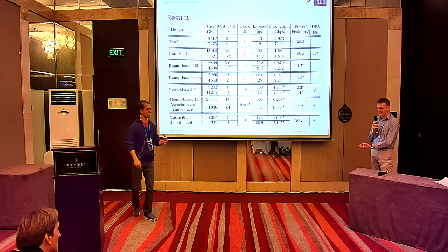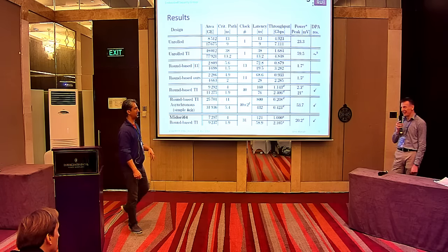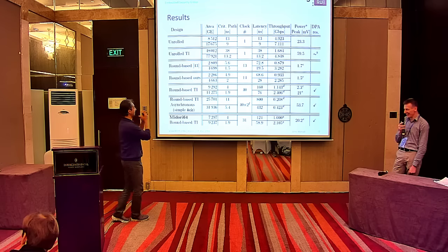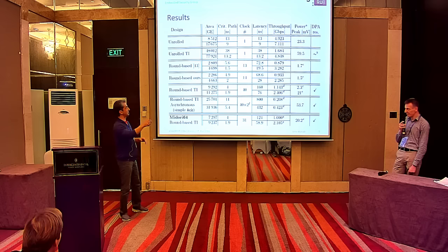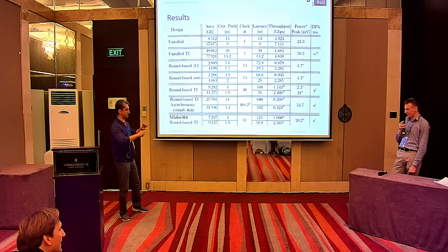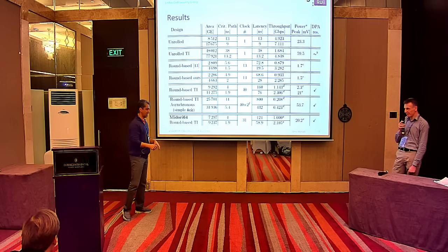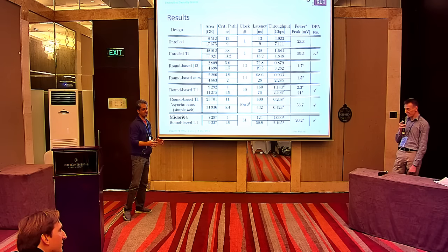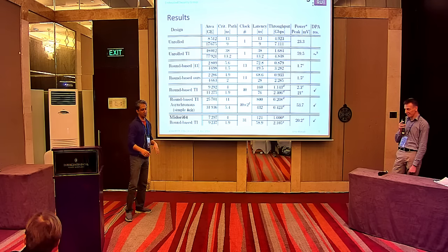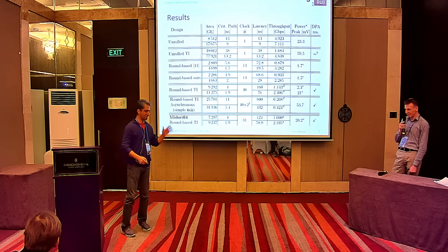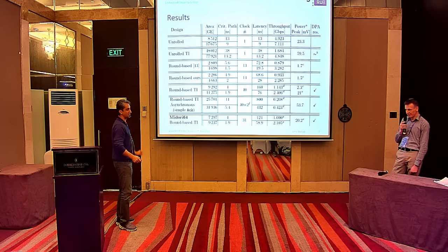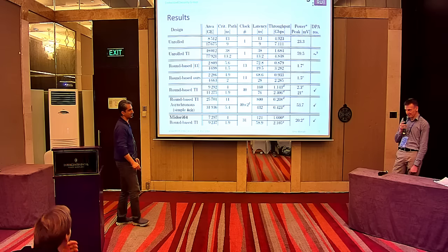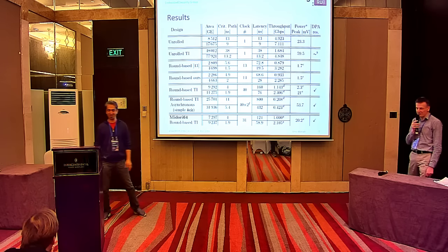You mean doing the simulation? Right. No, we have not. It would be too time-consuming or impossible. The problem is the time. If you want a good simulation, you need to simulate in the transistor domain and take every trace, which may take, in the fastest way, a couple of seconds, and then having 1 million or 100 million traces would not be feasible.